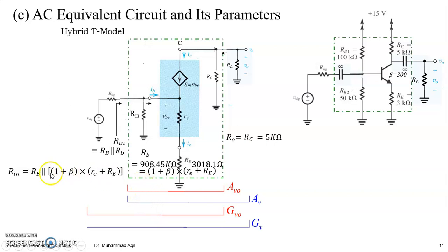So when we find the parallel combination of this resistance input at the base, R small b, and the discrete component based Theveninized resistance, we get almost the same resistance here. Why? Because this resistance is very high. It means our input resistance is depending on this one, right? So this is actually reducing the overall input resistance. Otherwise, the input resistance is very high, right?